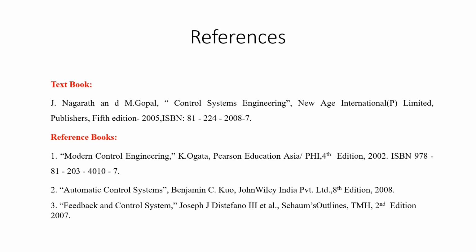In the multiple inputs block diagram representation, whenever we are finding the response for one particular input, the other inputs should be made equal to 0. You keep one input, the remaining inputs are made 0, and the same thing is repeated. Once the response for all the inputs is obtained, you have to summate all the output responses, superimpose them, and find the total response for the system.